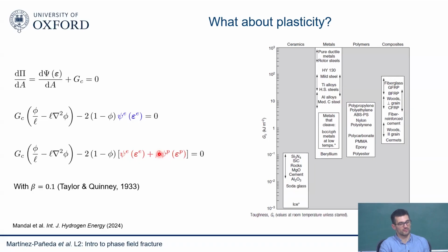So at some point, you may wonder, when does the Griffith energy balance break down? Thermodynamics might always apply, right? You could have a situation where you have a lot of plasticity, and you're heating that area. Then, if you want to draw a full rigorous thermodynamics picture, you must build that heat balance into the picture. We don't look into that because we're not looking into those kinds of problems. But I agree, if you wanted to, you could in principle, with thermomechanical calculations where you calculate where the heat goes and so on.